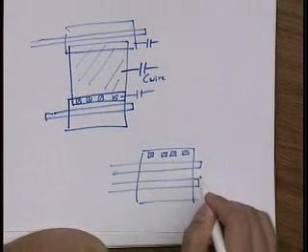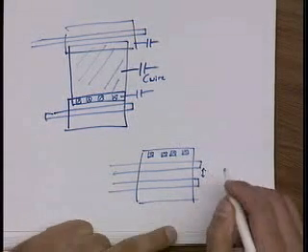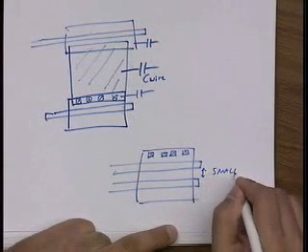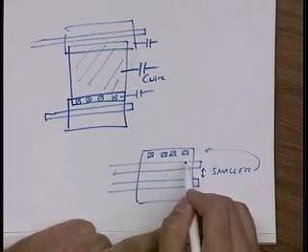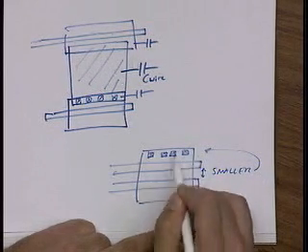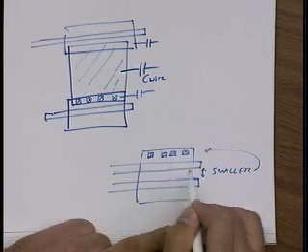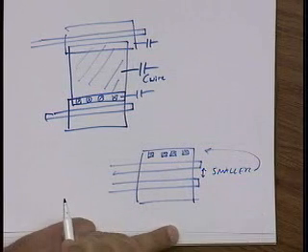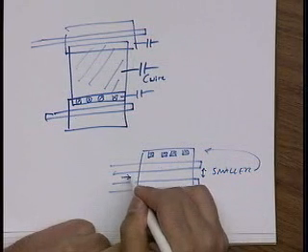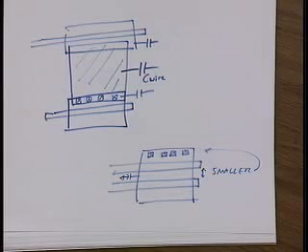Here I don't put contacts, and that means that this actually is even smaller than this. Because if I put in a contact, the design rules tell me I have to surround it with some extra space. So here, since I don't have a contact, this can be very small. And so the capacitance from this node to ground is minimized.